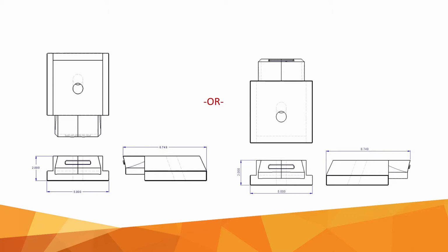The drawing on the left was made with third angle projection, which is what is taught in North America and probably seems normal to my audience today. The drawing on the right was made with first angle projection of views. And this is how drawings are made in Europe and some other areas of the world. But for those of us used to third angle view projection, first angle projection seems very backwards.